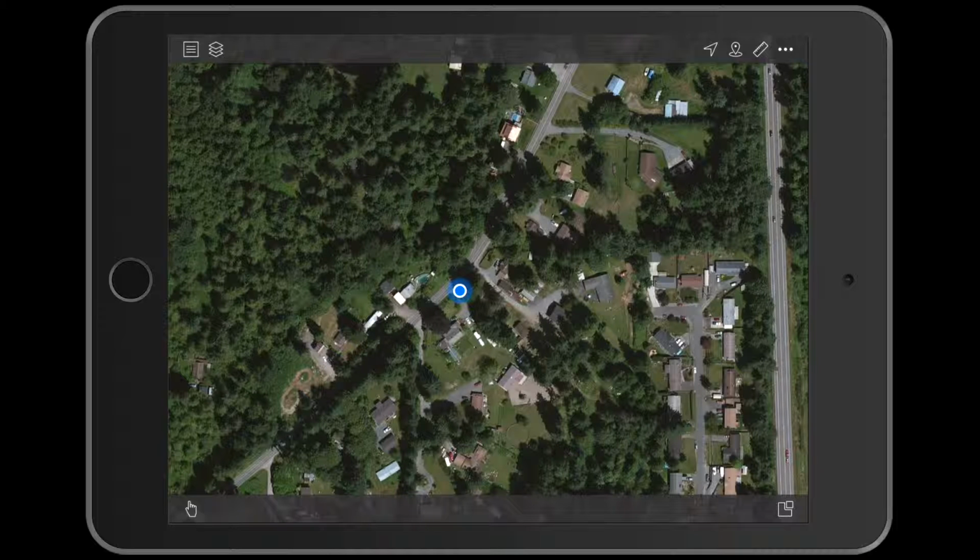You may associate unlimited date, timestamp, photos, and notes to any drawing. These are default feature data fields automatically provided by Apex, accessed anytime after you save your drawing. Apex also automatically creates feature data fields listing dimensional data about each drawing you create. For point drawings, there's a latitude and a longitude field locating the point. For line drawings, there's a length field. For polygon drawings, there's a perimeter and an area field. You may not directly edit these dimensional data fields. They are automatically edited if you edit the drawing, and if you change the units of measure, the values are automatically recalculated and labeled.